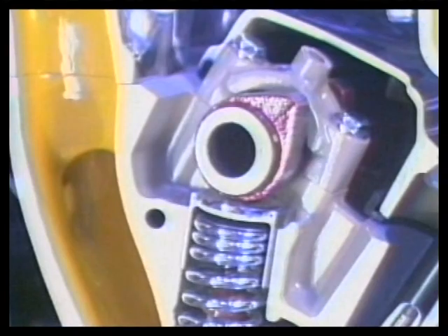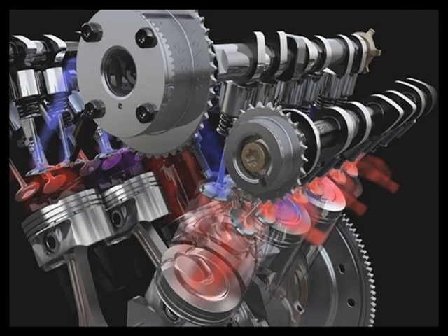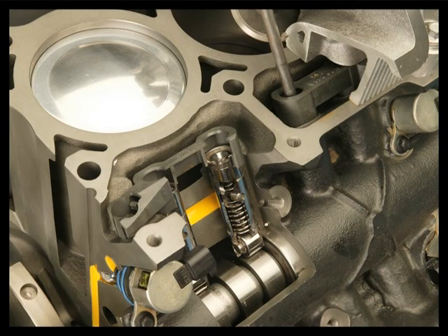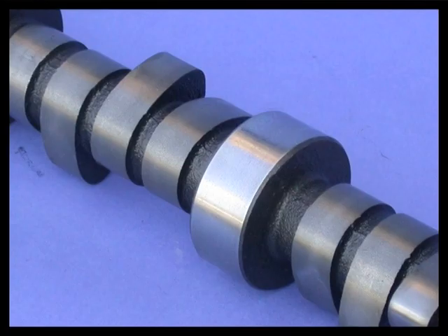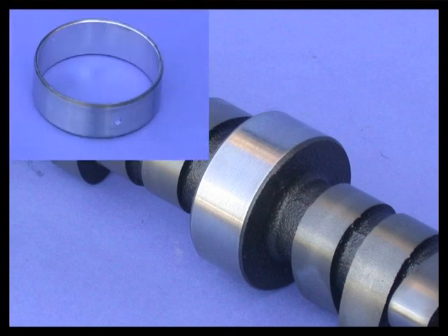A cutaway view shows how the camshaft mounts on the top of this cylinder head. Some engines use one camshaft. Some can use 4 camshafts, as in this high-performance engine. The camshaft is mounted in either the cylinder block or in the cylinder head on cam journals. The cam journals ride on cam bearings, similar to rod and main bearings.